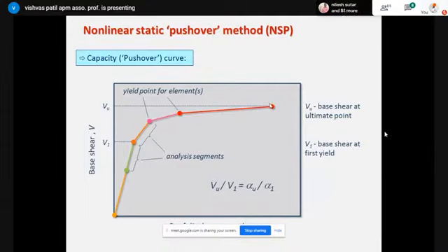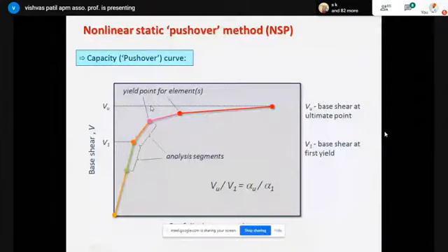So in the case of earthquake resistant structures, the design for earthquake resistance is nothing but increasing the performance in such a way that the inelastic displacement should be more, so that the structure becomes more and more ductile. Actually we are not designing for ductility. Ductility is achieved in the structure by means of the provisions given in IS 13920. By means of reinforcement detailing we are achieving the ductility.